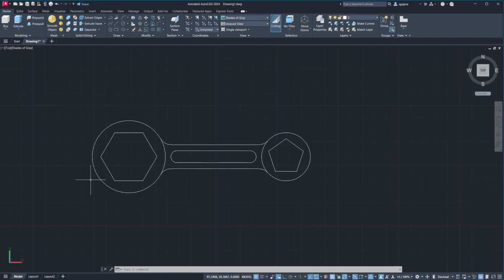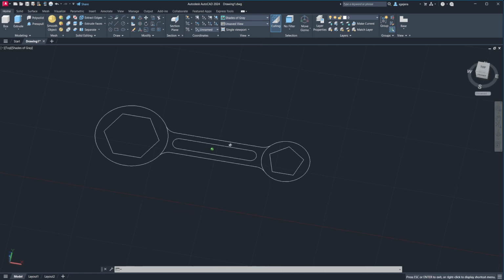So, most of the tools will work without even changing our 3D axis. This is called the world coordinate system. In the world coordinate system, the ground is the XY plane, and as you move up from the ground, the direction perpendicular to the ground is the Z-axis. Okay? That is our default, the WCS. But there are cases wherein we want what we call a UCS, or user coordinate system, wherein we need to change our XY plane so we can manipulate objects the way we want to manipulate them. For now, the world coordinate system will be enough for this particular exercise.